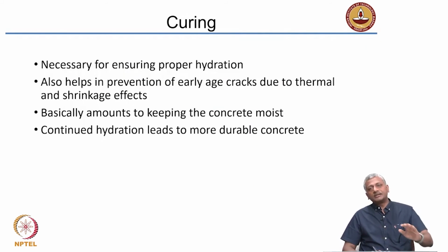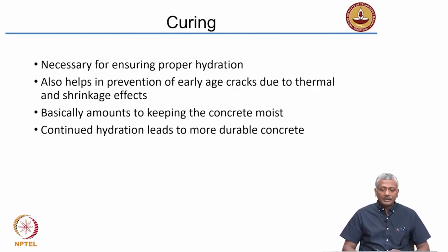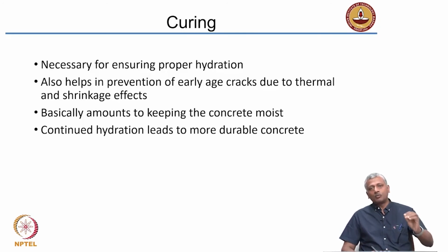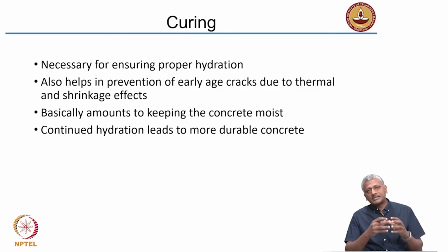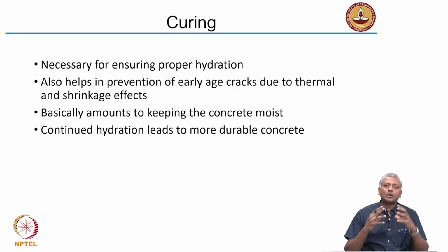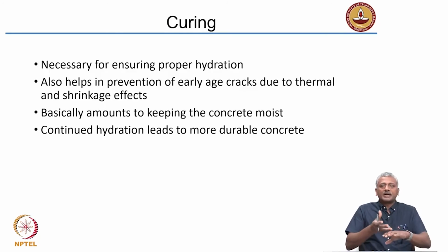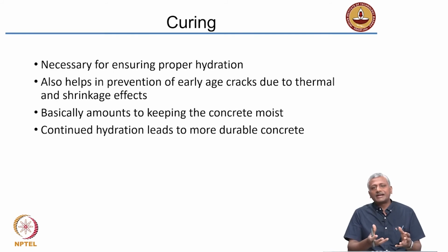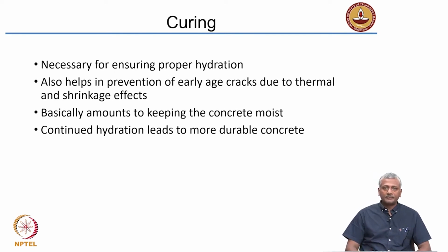Okay, after finishing is done, the next step is curing, and curing is absolutely necessary for ensuring a proper hydration of the cement. So, you put in cement, water, stone and sand into the concrete. The cement and water have a certain proportion, in such a way that the water is required for reacting with the cement and producing this hardened concrete structure. If this water starts evaporating even before the cement fully reacts, then it's not going to be good for your concrete. So to ensure that cement hydrates properly, you need to cure it.